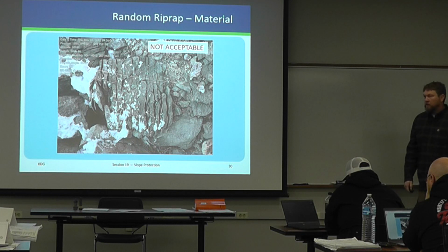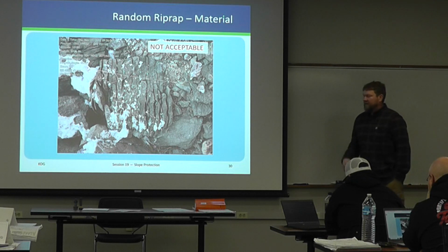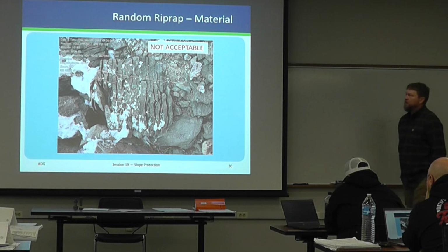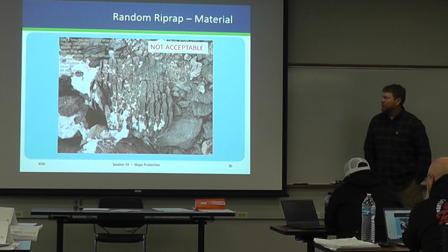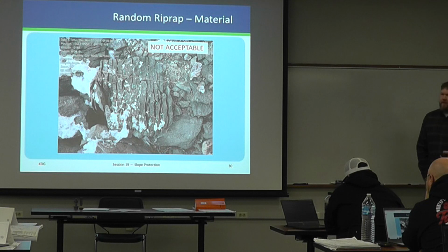So if that was a year later, how would you know when they actually brought it out? Well, that's where I really lean on the geotech folks to help with that testing. It's probably more knowing what pit it's coming from. Some may be more prone to it than others. But this one was a year or two after construction, and I'm sure that it didn't look like that when it was placed. Maybe it had indications of it, but just be on the lookout for that. So this would not be acceptable.